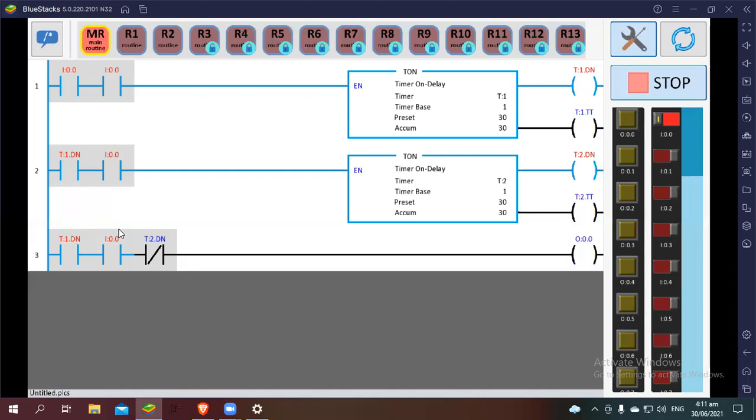Okay, so it now goes back to 0. The only problem that we have here is that we should have a momentary reset position if we want to do this one automatically. So yun yung concern lang dito. Unfortunately, this timer on doesn't have a reset button or a reset input. So the reset is actually also engaged with the enabled pin.